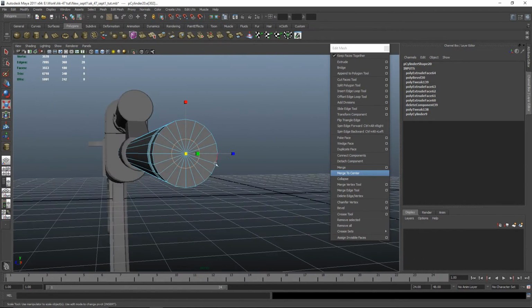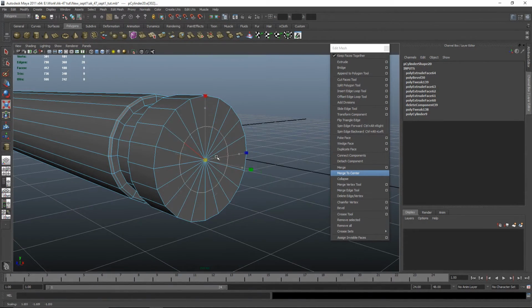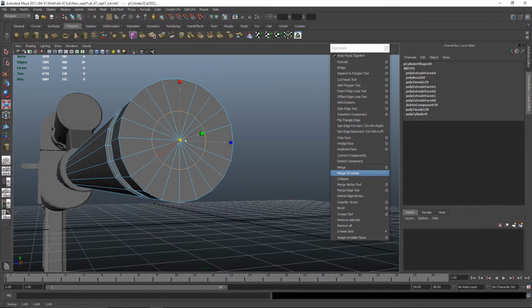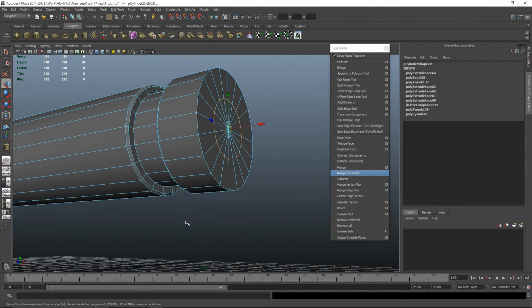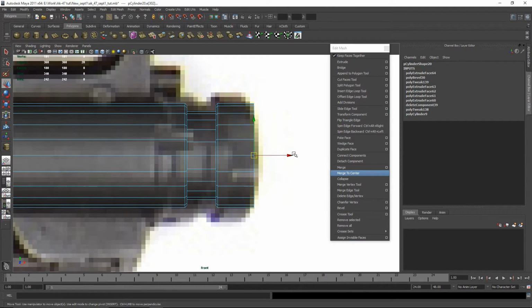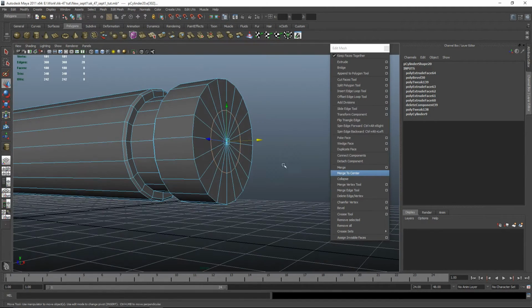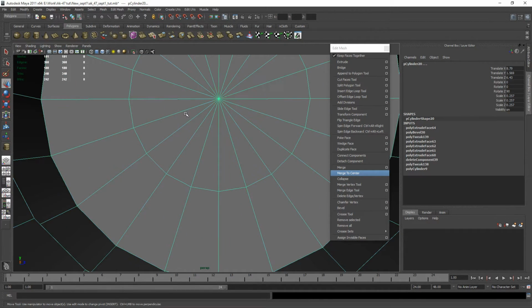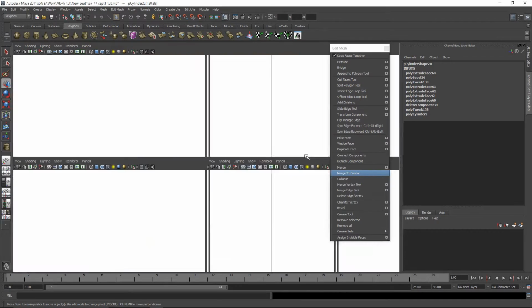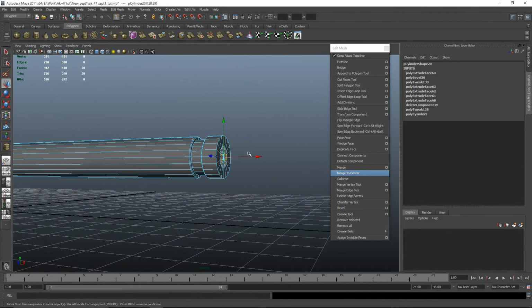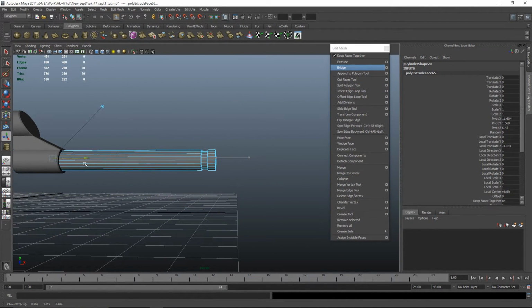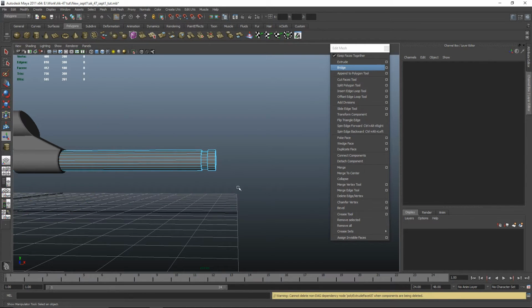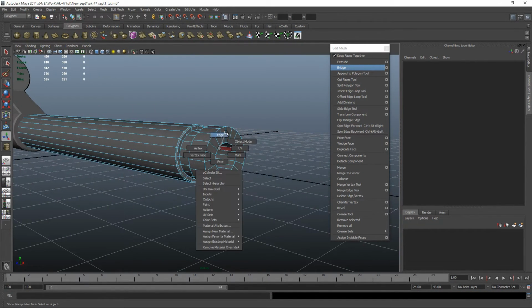Want to make the offset smaller, so just select that edge and just make it smaller to about this much, I think. Yeah, about this much. And make sure that's snapped, that's fine. I'm just going to go inside, select the faces, and extrude all the way in, and delete the faces inside, like so.